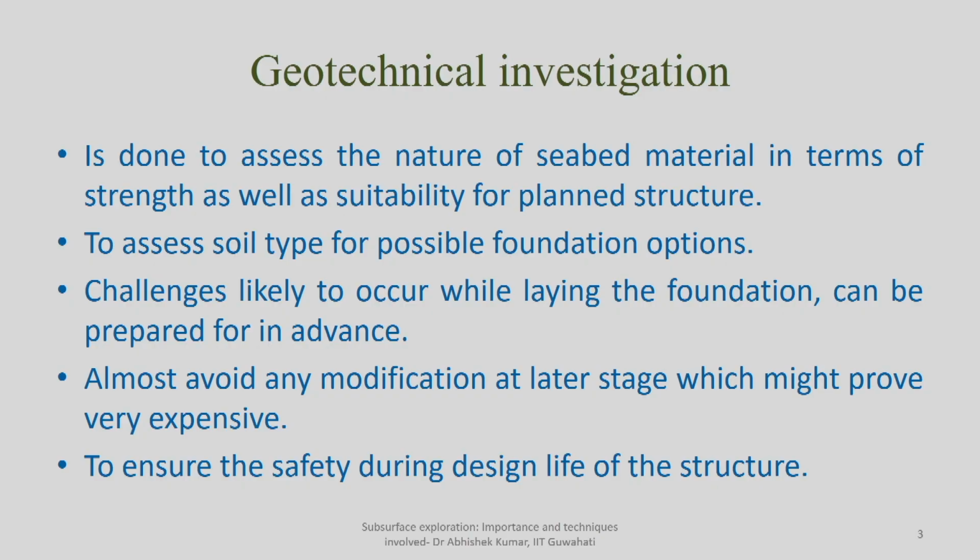So, unlike onshore, where we go for geotechnical and geophysical investigation in parallel to get more confidence and to get soil samples, in offshore we go for geotechnical investigation once, based on your geophysical investigation, we find that the site requirements are positive or supporting the site selection for the particular project. Then we can go for detailed investigation, and we can put in whatever investigation cost is needed. So, that is one thing.